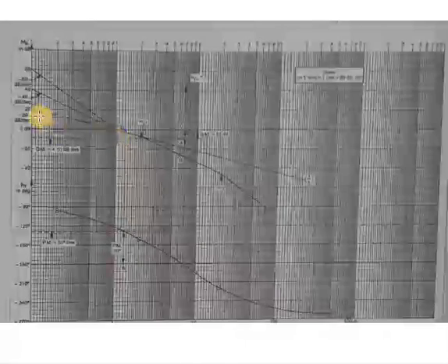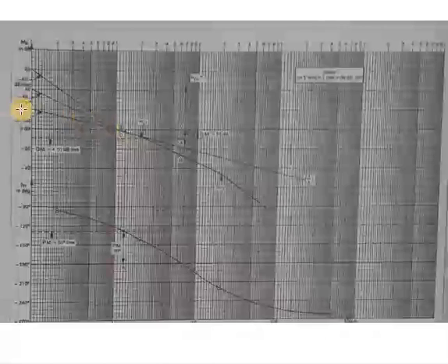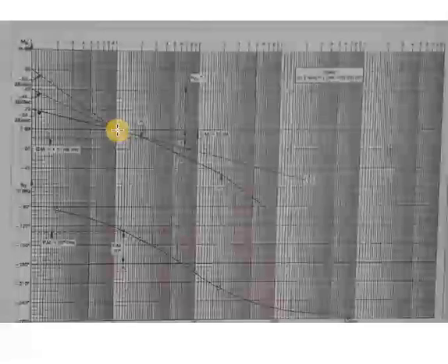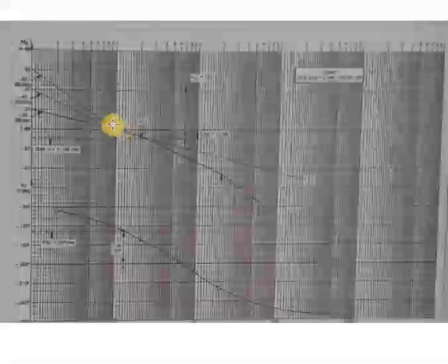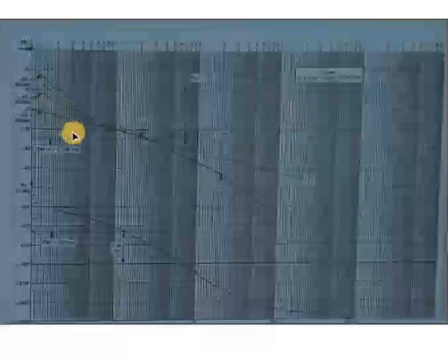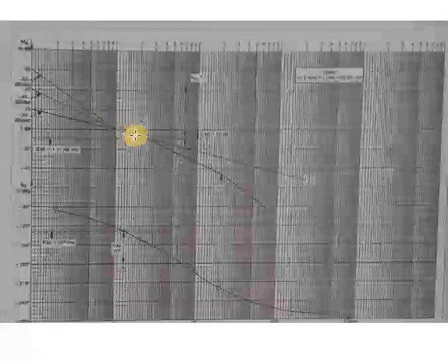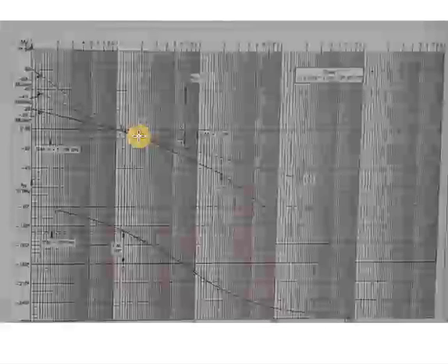So first we'll draw the plot without K. It will start from minus 20 slope up to omega equal to 1 and continue with the same inclination up to the first corner frequency, that is omega c1, which is at 2 radian per second.